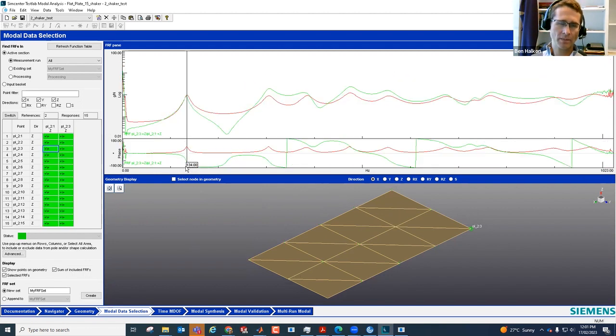I'm expecting to find a resonant frequency at 134 Hertz when I do the analysis, and a mode shape associated with that. The processing will also extract some amount of damping, and we can have more damping in some shapes than in others. The real way that we will determine the damping is by performing the modal analysis.